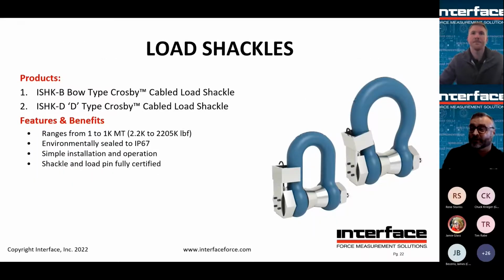We also have load shackles. Again, lots of people are using shackles in lifting. This would be basically replacing a Crosby shackle with a load measuring version of it. These are available in either wired or wireless. They have very high safety factors. Again, with overhead lifting, there are always requirements. You definitely don't want to drop the load.